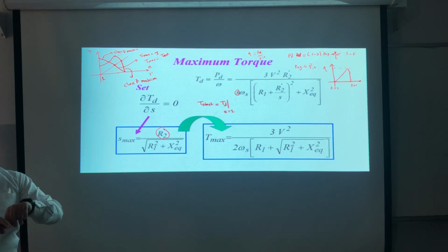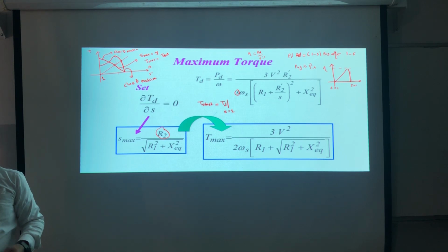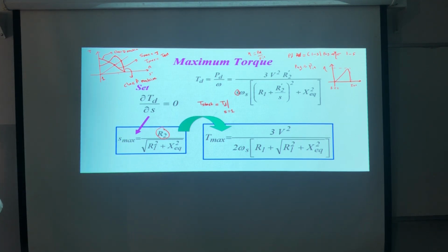Moving parts interact with each other. Of course there will be friction. But this friction is very small. Someone will say, you are neglecting the copper losses on the rotor, for example, here. But this is the ideal case, in order to judge the efficiency from the slip.